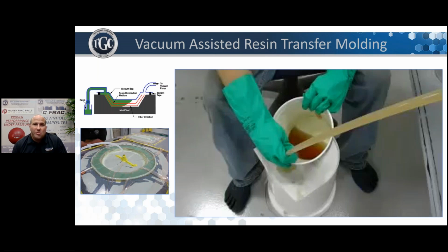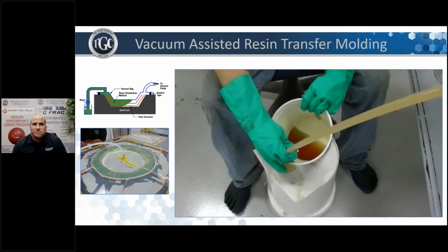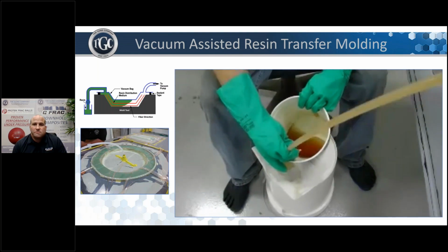How does it work? Fiber reinforcement of different types can be hand laid up into the A-side rigid mold and vacuum bagged on the B side. The vacuum draws the resin through the fiber. The initial curing usually takes place at room temperature. After demolding, a post-cure can take place to further enhance the properties. This short video shows how the resin is pulled into the fiber using vacuum, with the reinforcement holding little extra resin.